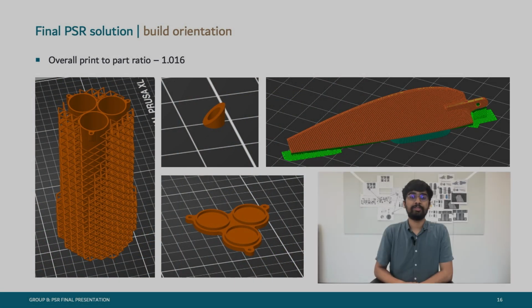In designing the lattice structure for optimal 3D printing efficiency, the build orientation is set vertically, thereby eliminating the need for any bridging or overhangs that could compromise the structural integrity. Propellers are strategically mounted on the thin airfoil sides at a precise 90-degree angle relative to the horizontal plane, facing the side devoid of grooves to ensure that no supports are required on the plane, streamlining the manufacturing process.